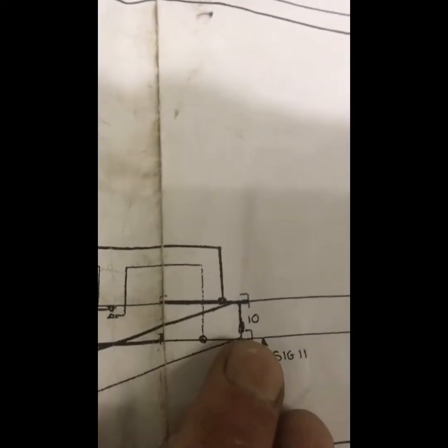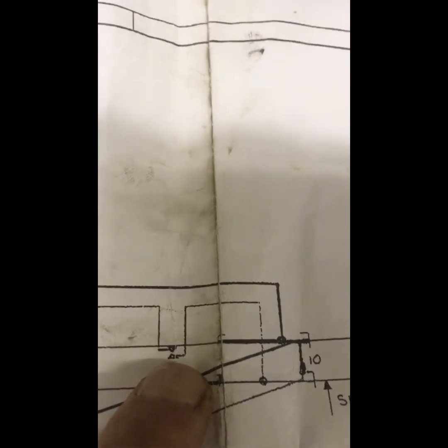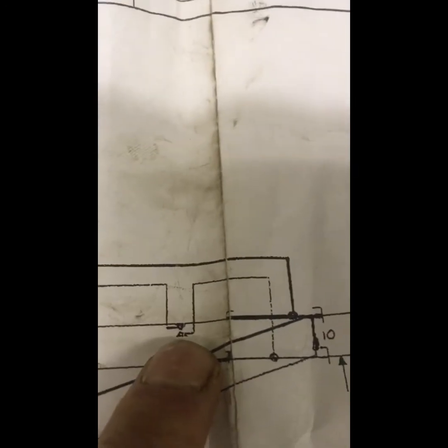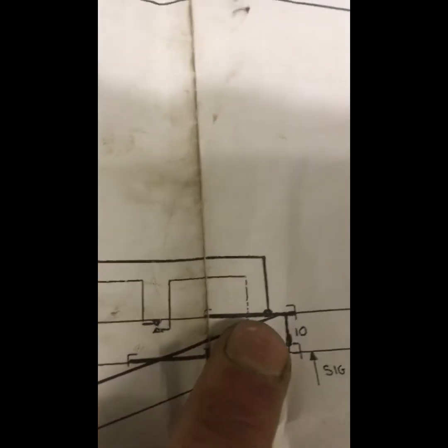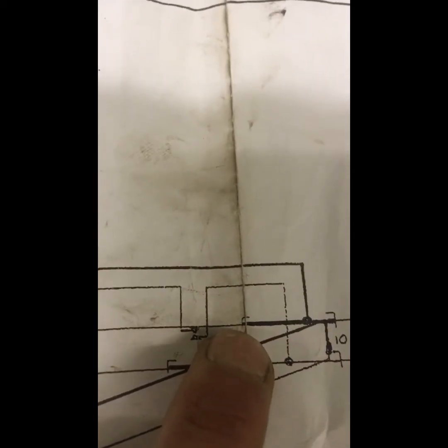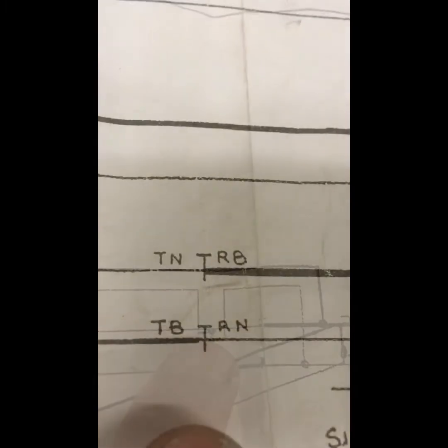If we follow up through these track points here, we will notice that we have an insulated interrupter on that track circuit, and I'll show you what that does in a minute. Basically, if the train goes beyond the limits of the track circuit, it will shear off this insulated track circuit interrupter and occupy the track circuit permanently.